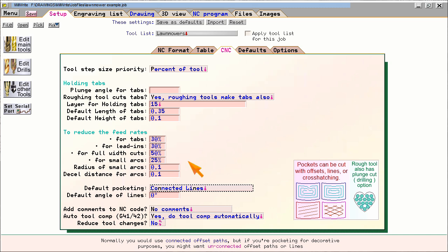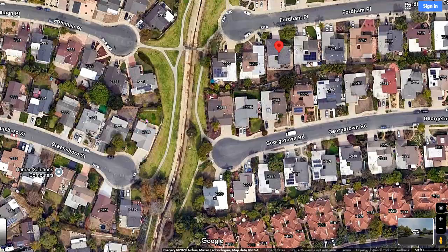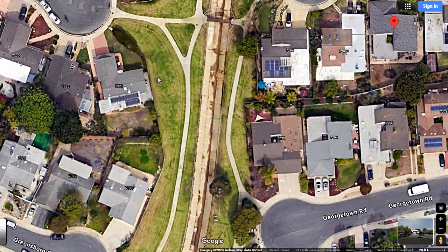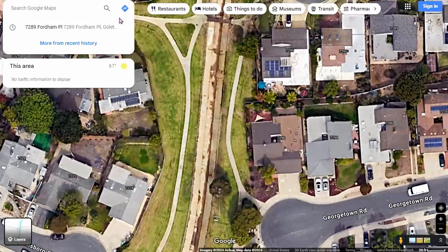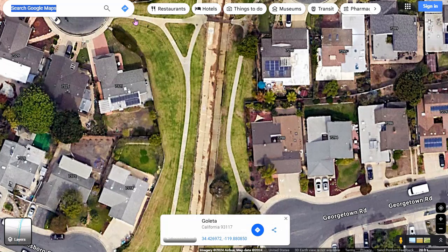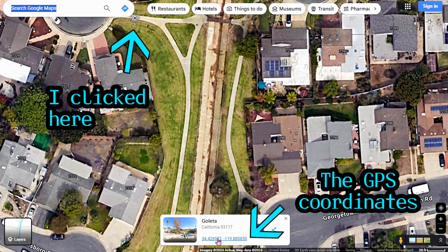There are different ways of defining the area to mow. The most accurate method is for someone to walk around the boundary of the grass and collect GPS points, and then import those points into the software. The Google satellite map will display the GPS location where you click, although it requires a bit of clicking before you get the location, and it doesn't have the option to save the points in a file, so it requires a lot of copying and pasting.